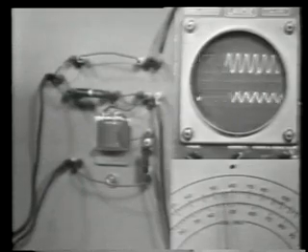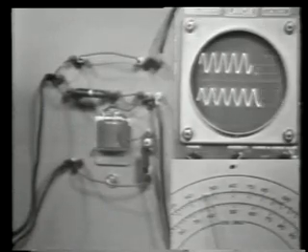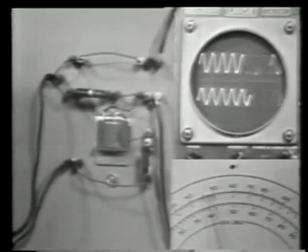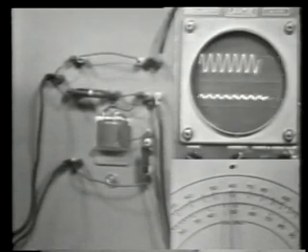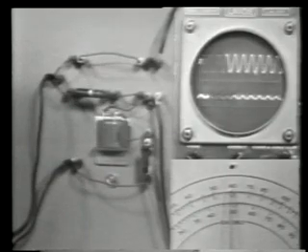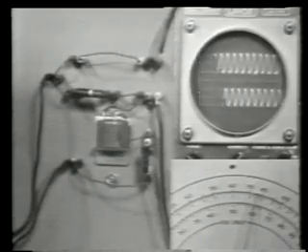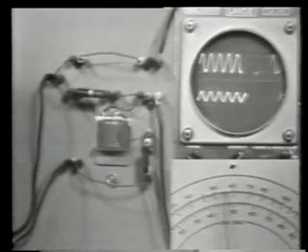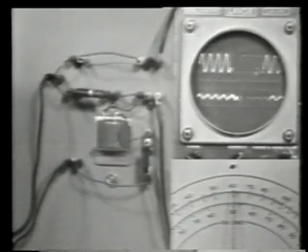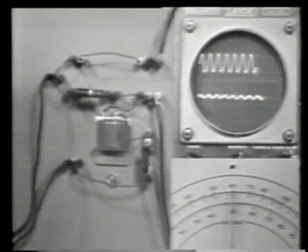All right, at frequencies below about 500 hertz, the output from the filter is maximum. However, when we approach 600 hertz, the output drops off to practically nothing. Above 600 hertz, though, the output rises to maximum again. This filter, then, the band reject filter, is now rejecting a band of frequencies around 600 hertz, but passing all others.